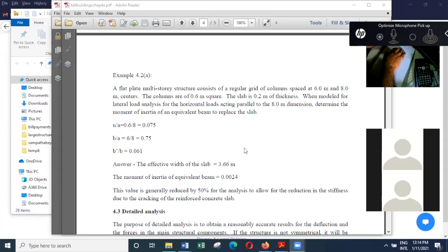But before that, when you look at tall buildings, all these buildings are subjected to lateral loads, and we have already done one example using coupled shear walls. One of the problems that occur in tall buildings is that they are all cantilevers almost fixed at the ground level. So when you have a cantilever, it will deform when it is subjected to lateral loads.